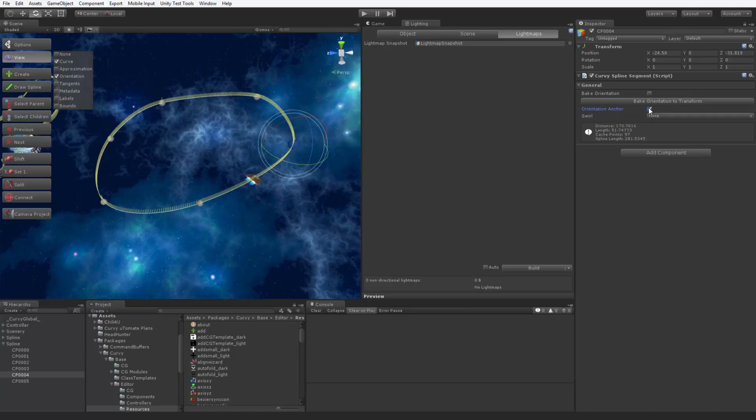Rotating the control point to influence the orientation is a bit inconvenient though. After all, the z-axis is not matching the spline. But there is an option that can fix that. Control point inspectors in the static and dynamic mode offer, as you can see, an option to bake orientation. What this does is snapping a control point to the spline tangent axis, making rotations on the axis the only input needed to define any orientation. This makes any setup faster.